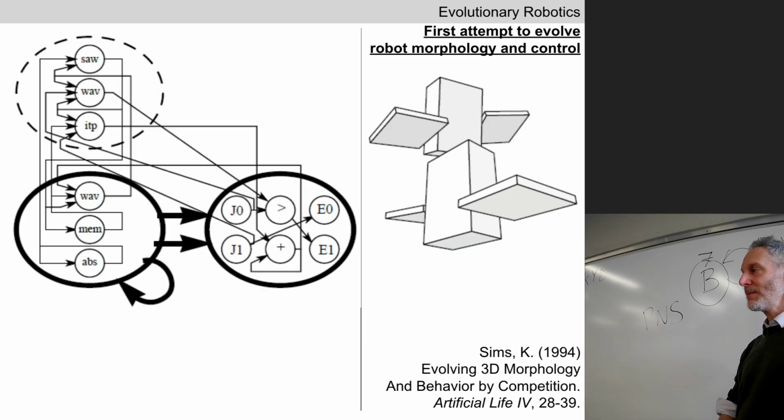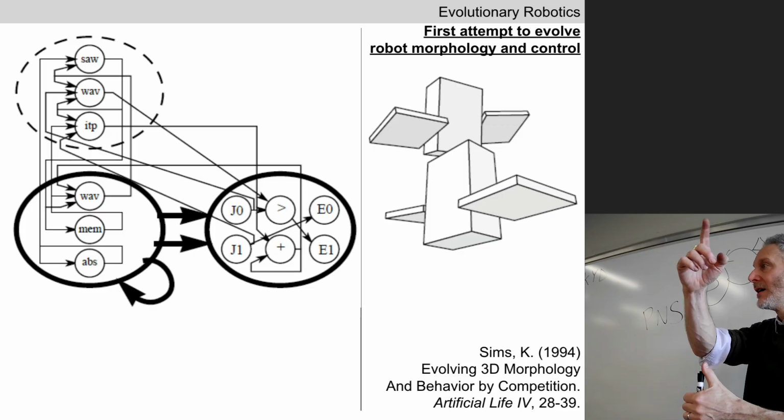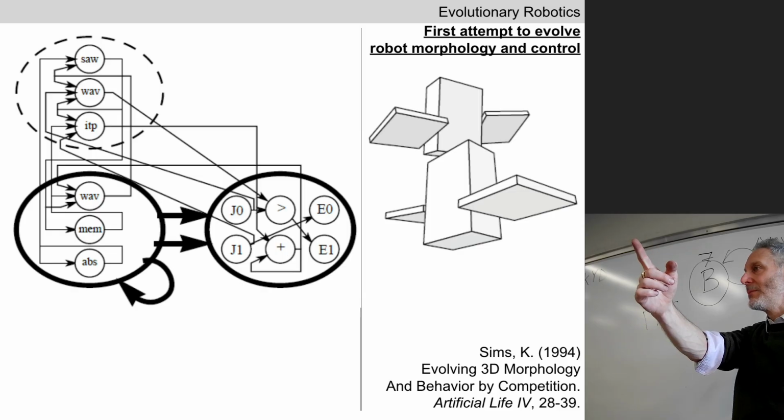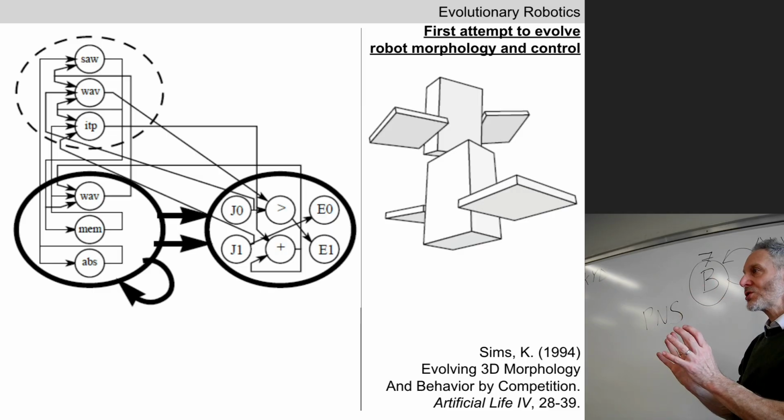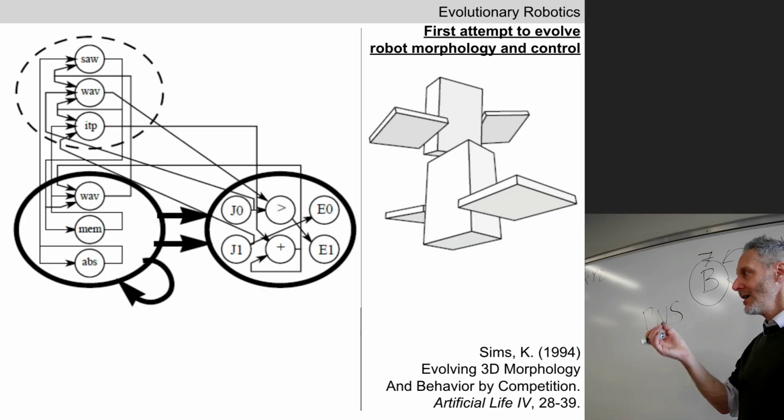The activation function. So the genotype is saying, put a neuron here, and when you do, assign it an activation function of the absolute value. So in this neuron, while the robot is behaving and values are arriving at that neuron from its incoming synapse, like every other neural network on the planet, that neuron performs a weighted sum. It multiplies the incoming values by the weights of those incoming synapses, and it now has a weighted sum, and it pushes that weighted sum through an activation function, like the absolute value, and the resulting value coming from the activation function is the value of that neuron at that time step in the simulation.